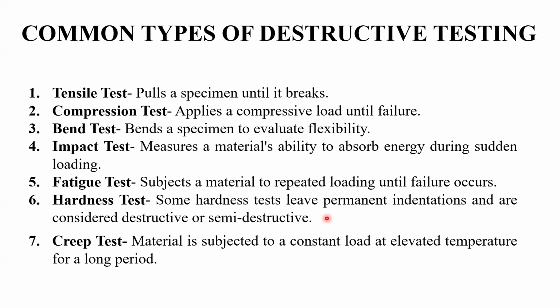A tensile test is where you pull the material or specimen. Mostly we will be using the material itself, so that it is easy for your understanding. So you pull the material until it breaks, or compress your material until it breaks, or bend it. So these three are a common thing, and can be done on the same machine.